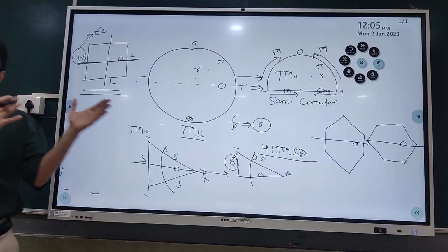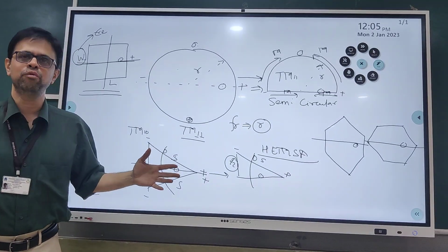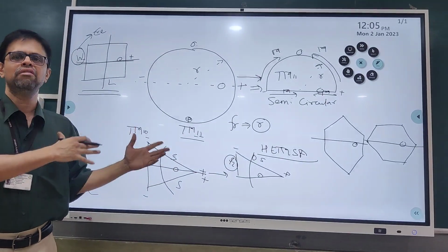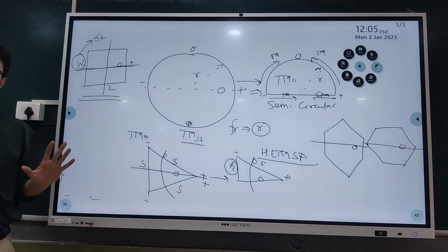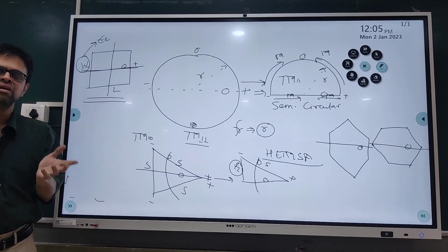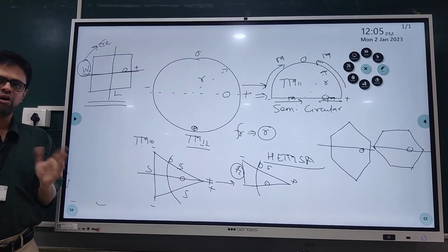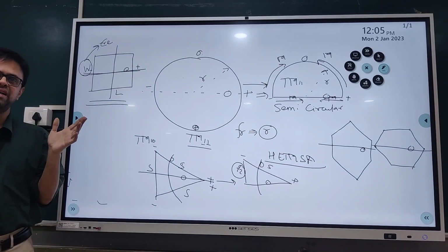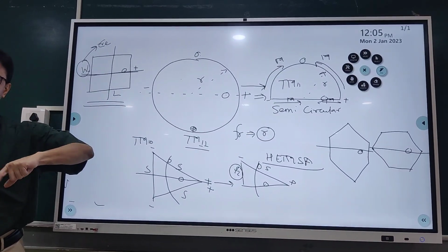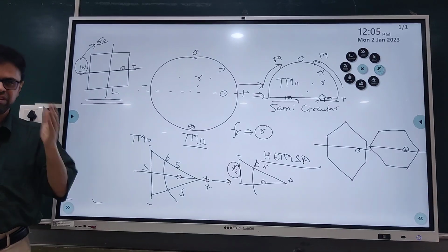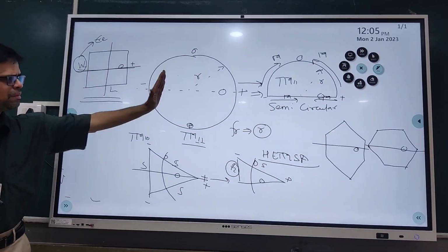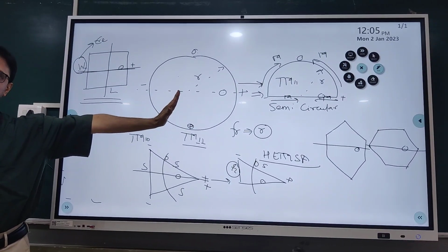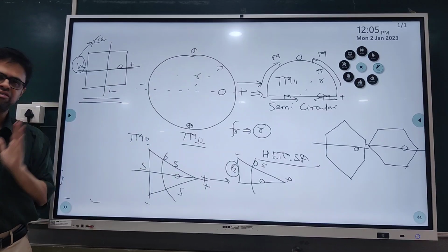For this, you need to understand how the magnetic dipole models are evolved, which we have covered in the basics of microstrip antenna, where we drew the magnetic dipole model for the rectangular patch. Using that, you can see why a radiating edge is defined and why a non-radiating edge is defined. With respect to the basic rectangular patch, the same explanation is applicable to the circular patch as well as the equilateral triangular patch.